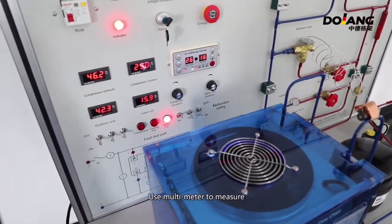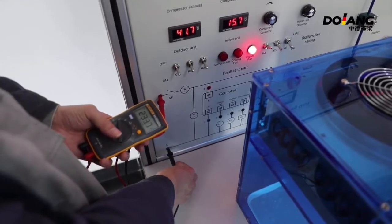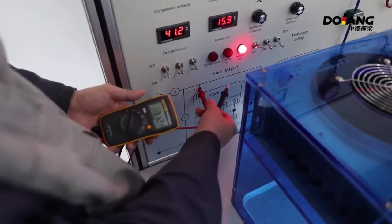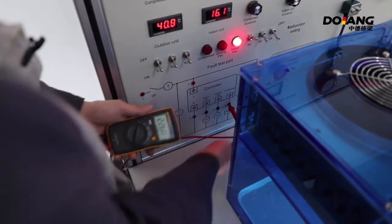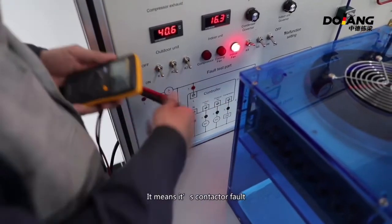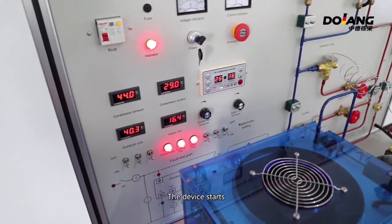Use a multimeter to measure. We found that there is no voltage at the contactor. It means it's a contactor fault. Turn K4 to on. The device starts.